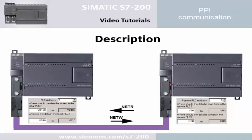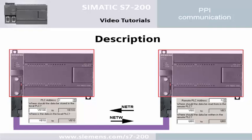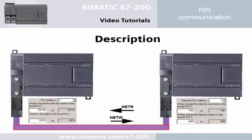Welcome to the SIMATIC S7-200 video tutorial for point-to-point communication. Using the function blocks network read, Net R, and network write, Net W, up to 16 bytes of data can be exchanged between S7-200 PLCs via the Profibus cable. The respective communication partner is identified by the address.